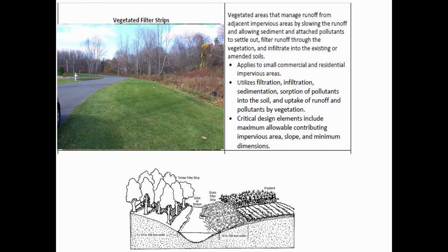And none of those things have a positive effect in the aquatic ecosystem. All those things have negative effects. So if you have that water flow over grass, then the grass can extract some of those pollutants and the sediments can settle down into the grass. And so it's better to have the pollutants hit the grass than it is to hit the stream, because the organisms that are in the stream are more sensitive.